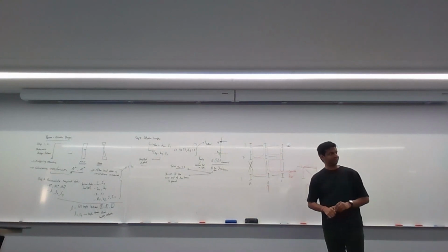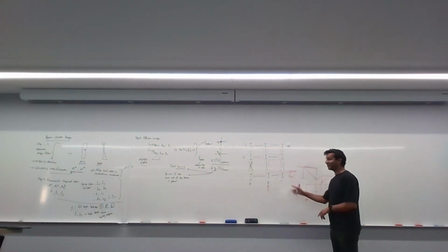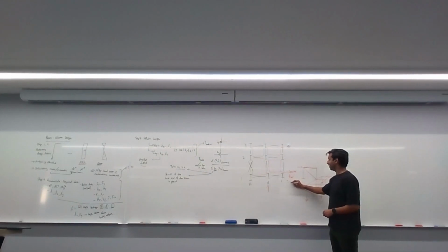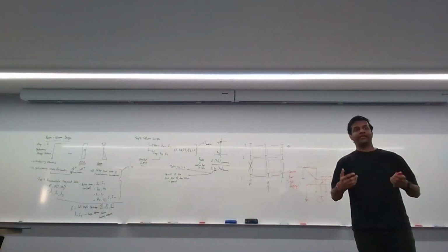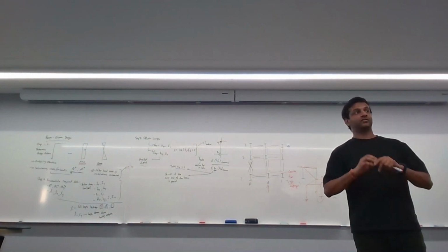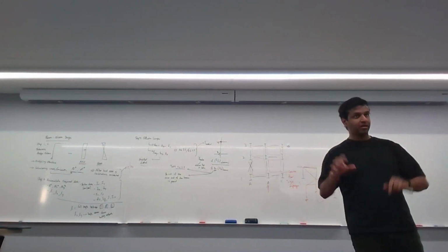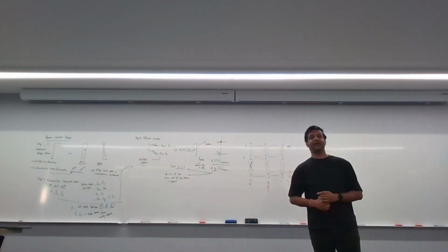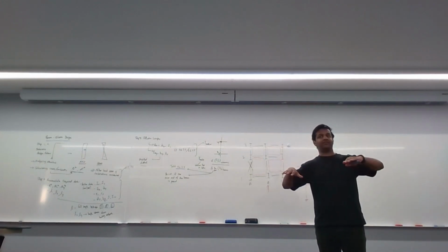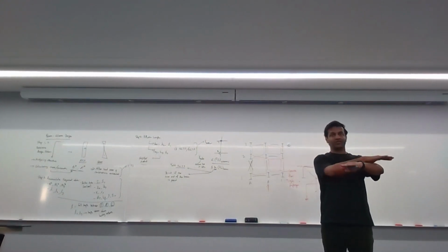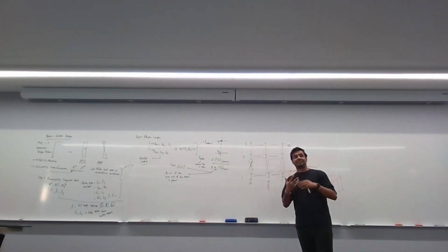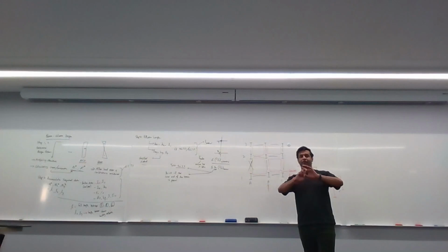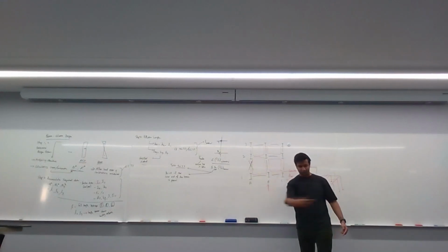Another version of that is called rigid diaphragm. If it's mentioned to you or you know that the flooring is a rigid diaphragm, it means the floor is rigid, it's stiff. The other thing is, what's a diaphragm? A diaphragm is basically any element that resists loads across a floor. So whenever someone mentions diaphragm, they're referring to the floor that is resisting forces moving across the floor this way.